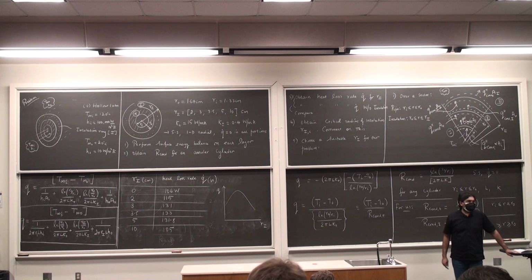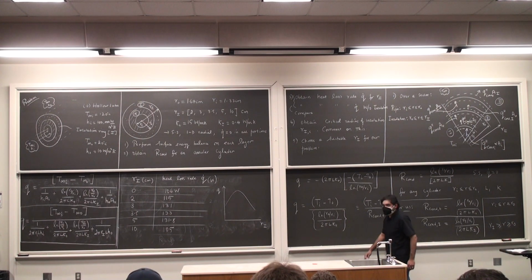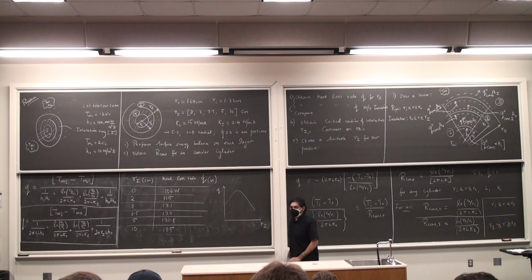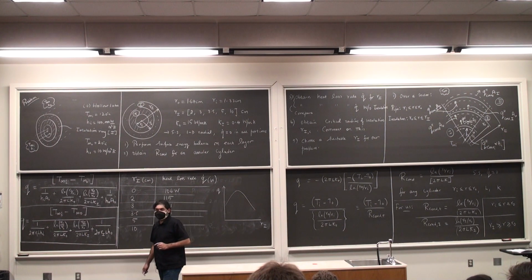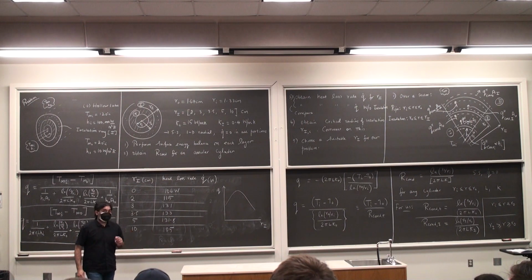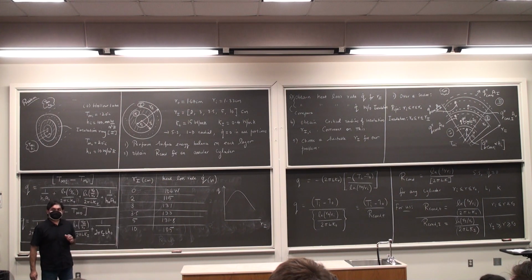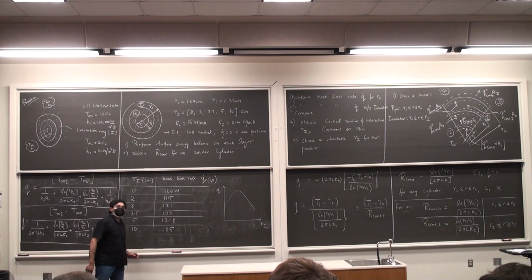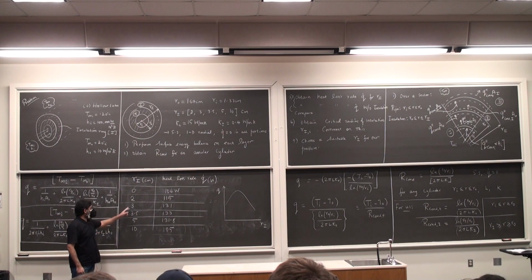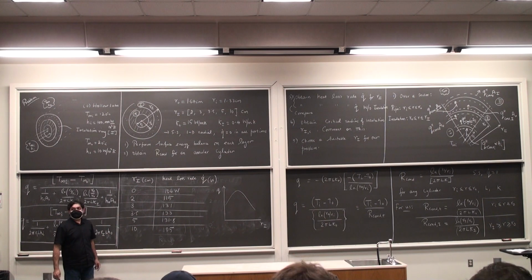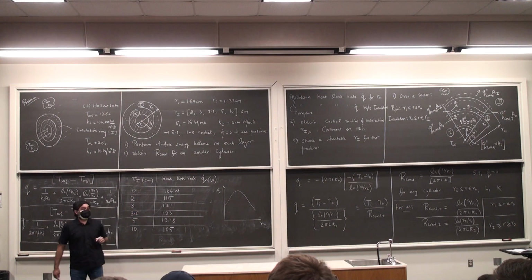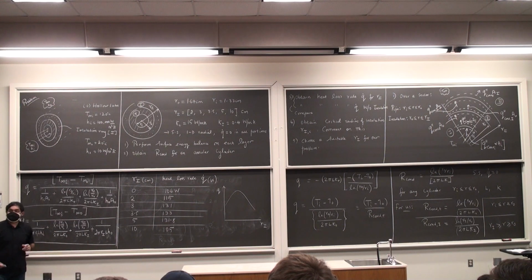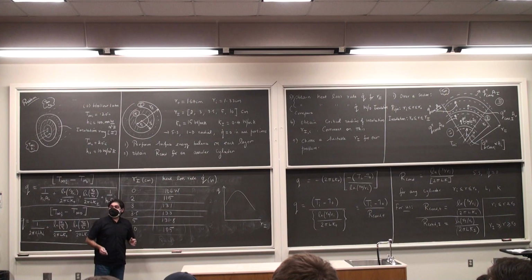So what does this tell you? Is insulation a good thing or a bad thing? Depends on what? Depends on the radius that you choose. So if somebody says, hey, just put some insulation and forget about it, your question should be, okay, what the hell is supposed to be the radius? If it is something like this or something like that, I'm actually increasing the heat loss rate. You see, for heaven's sake, that's not the same thing as having an insulation, right? When people say insulation, you're reducing the heat loss rate.